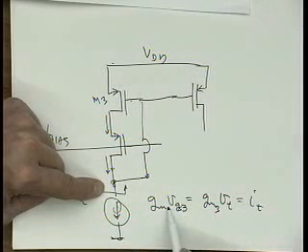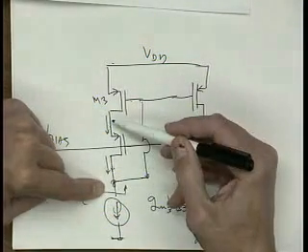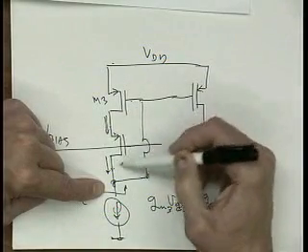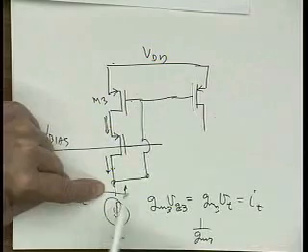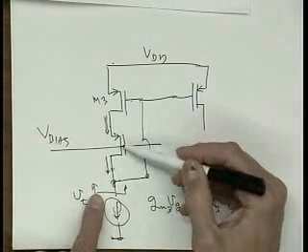And this is transistor 3. So what is the resistance looking up into here? It's just 1 over GM3. The fact that this transistor is here, because the current here is exactly the same as the current here, does nothing with respect to what I see looking into here. So this is just a good old diode-connected transistor that happens to have this transistor stuck in the center of it.